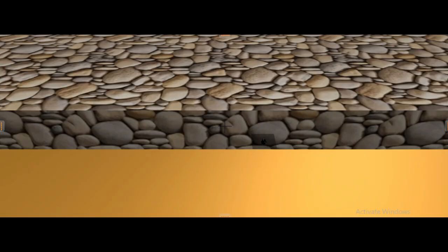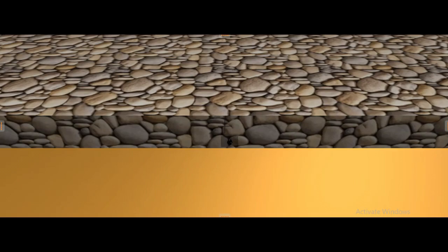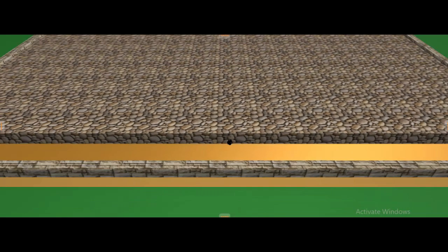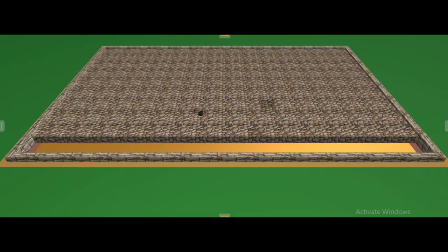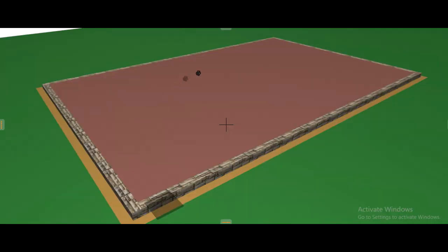So when I'm now squaring this one, I treat it as a cubic dimension, whereby I multiply the length times width times thickness, and that is the volume of this hardcore that I'm now carrying to the Bills of Quantities. Now, all these are blinding which has been done over the hardcore, and to square this one, you simply multiply the internal dimension, that is 11.60 by 7.60. So you get an area of 88.16,